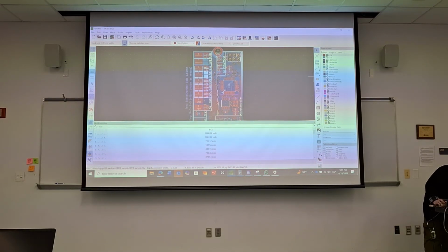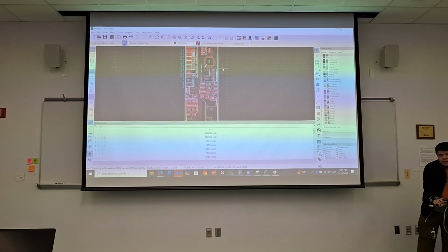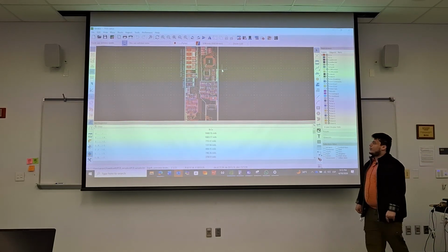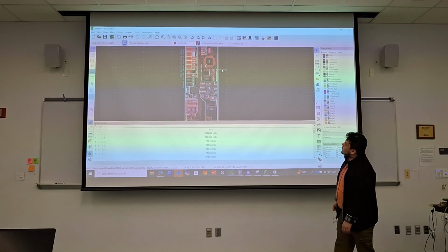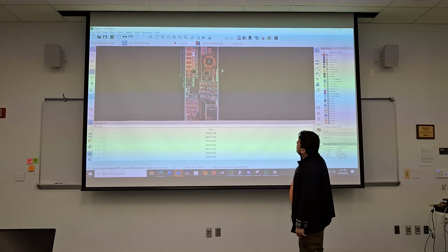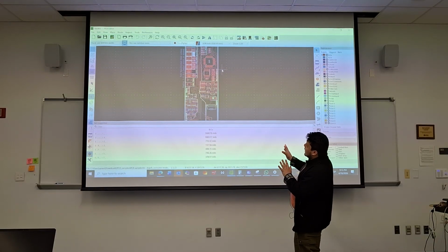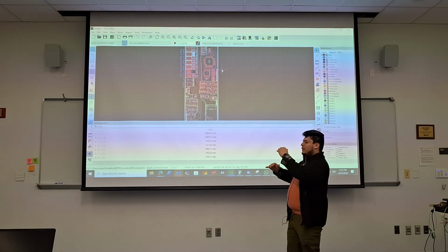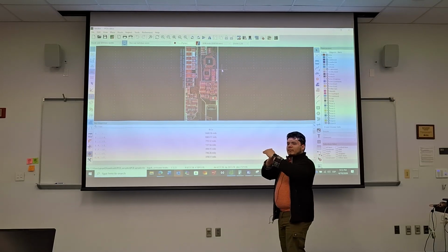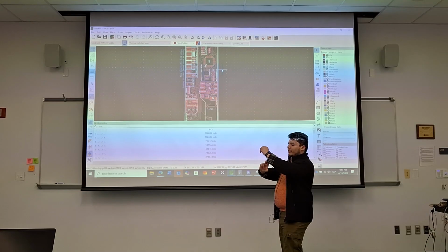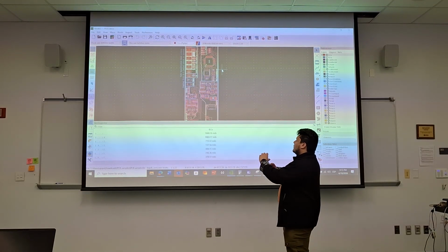So this is a board that I would not have minded seeing as a 4-layer. I see you were able to route a lot of your power, but routing the power is also kind of what led to a lot of the via transitions. So as a 4-layer board, this could look in two ways. You can keep what you have and then just put two ground layers in the middle so that you're shielding or referencing the top layer, and then all your bottom is also shielded with solid ground as a 4-layer board.